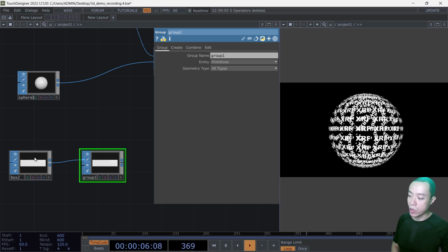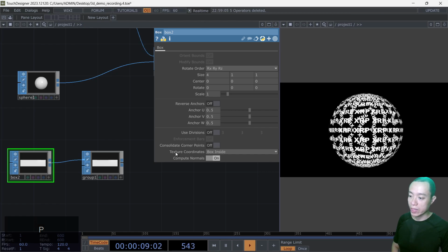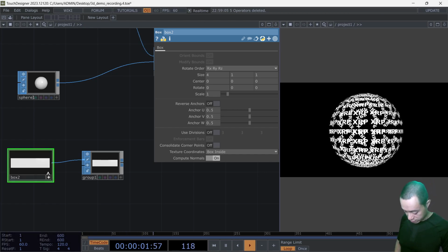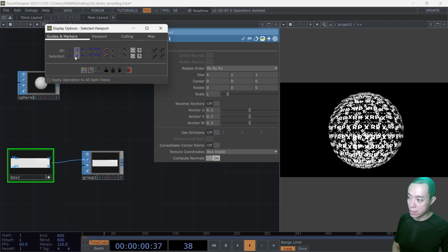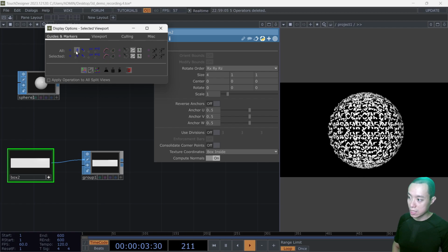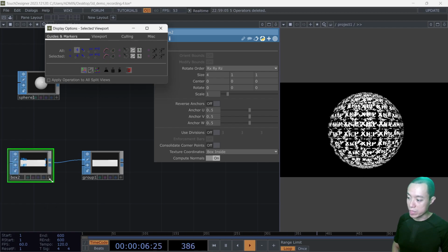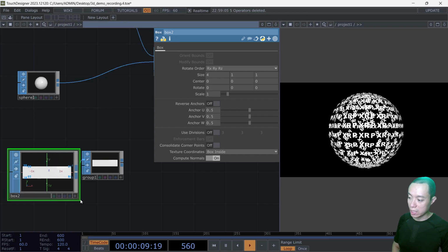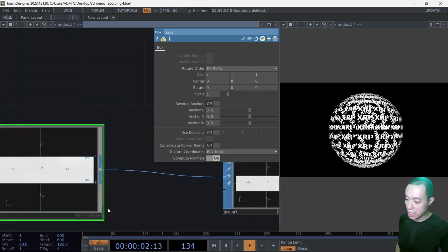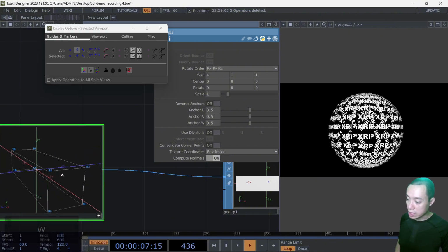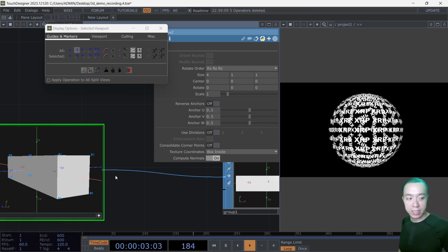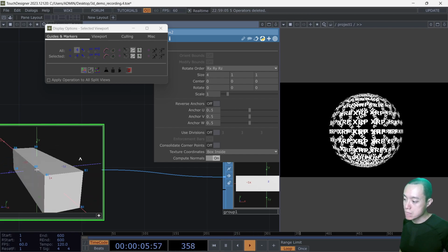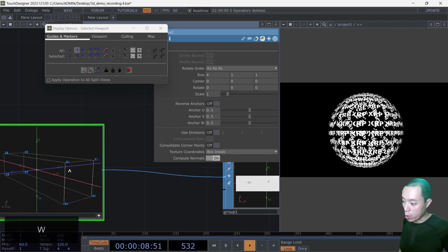Okay, now if you go into the box over here and you turn on viewer active, turn on points, okay, point numbers, you're going to see that the numbers will be displayed over here. Okay, and if you zoom in, move around, you're going to see all the points over here. If you press W for wireframe, you'll be able to see it. Basically, you're going to visualize the points over here.